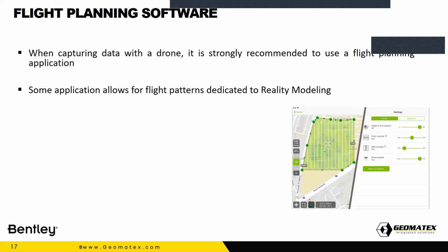And also, if you don't have any experience in flying drones, feel safe to fly your drone through one of those softwares. Of course, you should take care of the battery level, the wind, and other aspects: there are no animals around you, no kids, you are controlling the area you are taking off and getting back, and there are no high trees in your flight path or buildings. But you still could do the job if you are not 100% capable of flying a drone. You can still do the job with some training. So those softwares enable you to use the technology.